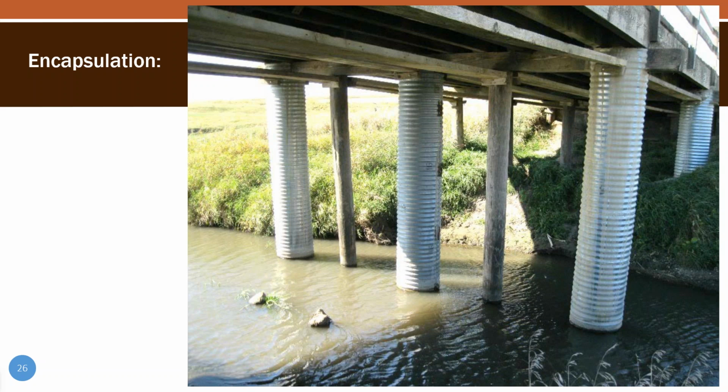My only other caveat with these ones is that if you live in a seismic region where there's any real concern for seismic, and let's just start with, these bridges were never designed for seismic, at least the vast majority of them. But if they still could be exposed to an earthquake, these encapsulated piles are way stiffer than everything else on the bridge. And so you're going to try and lock in a lot of load that maybe you weren't intending to as you happen. And again, seismic is probably not the driving design concern for these bridges.